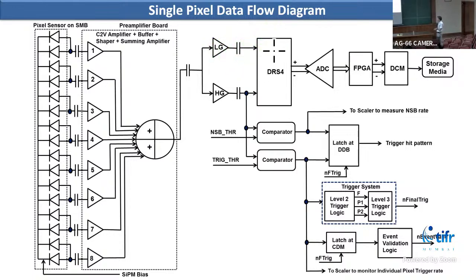But you also have ganging up. Ours, the transimpedance stage, is a discrete component. We are using a transistor-based circuit. So if you don't use the AC coupling, there is the biasing of the transistor. So that's why you have to use it.